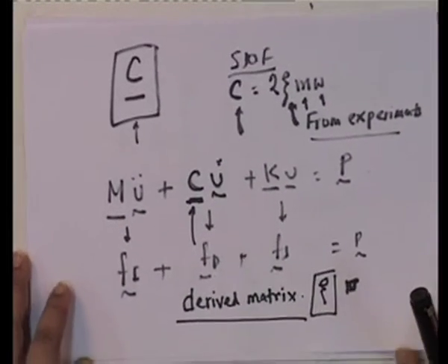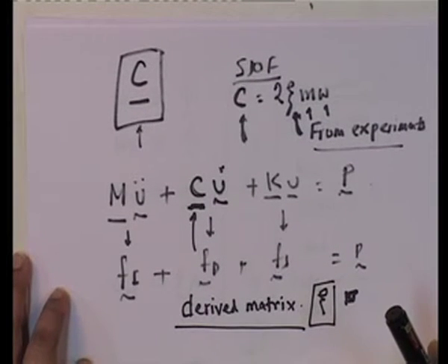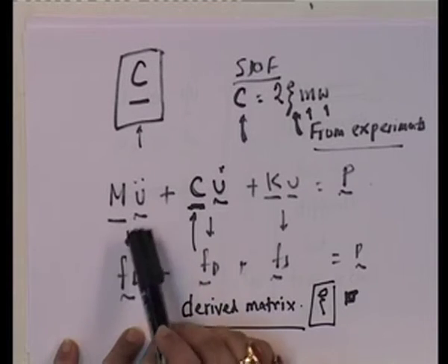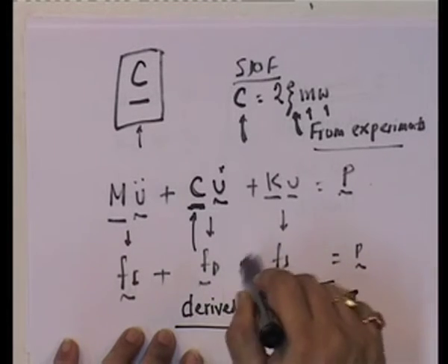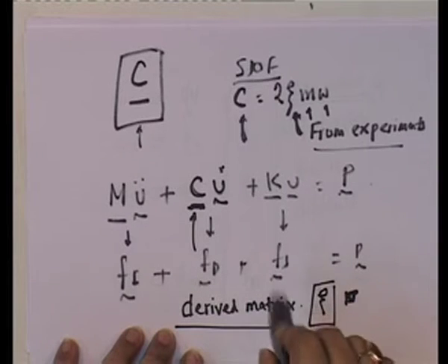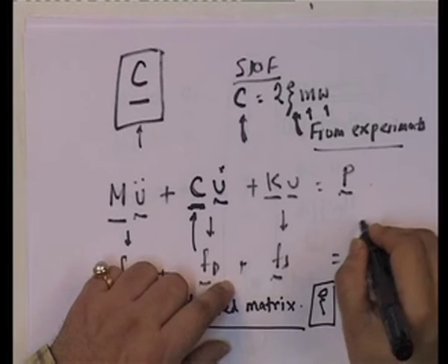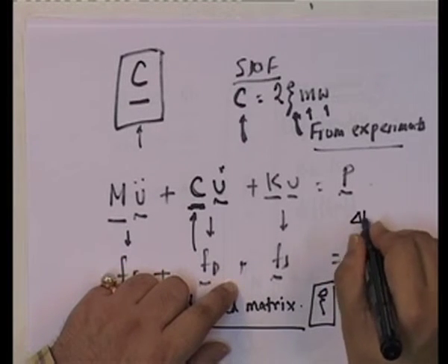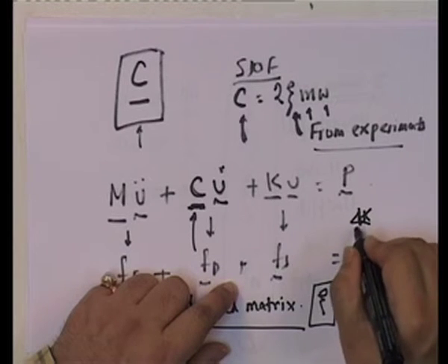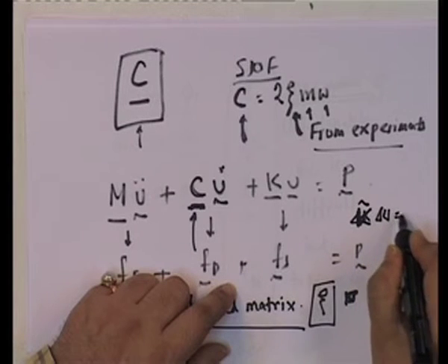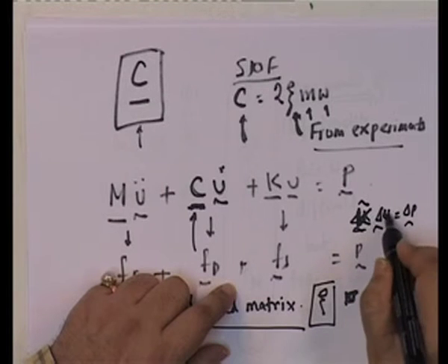Ultimately, remember I developed a numerical method, the Newmark-Beta method, the linear acceleration method. All that does is it sets up k tilde into delta v is equal to delta p, and that is how we found delta v.